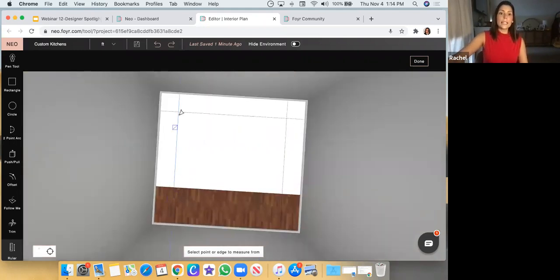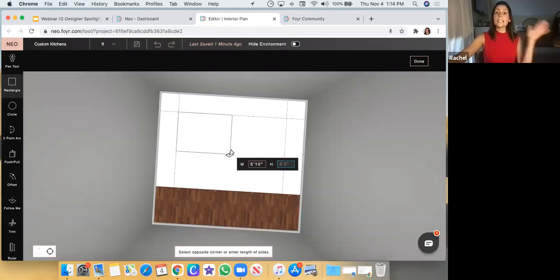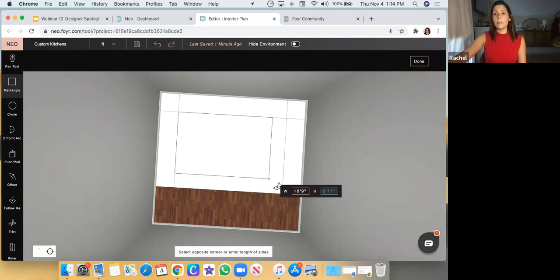Right? So now I have a nice dotted line guide that now I can draw over top and start to define the different areas. So I can use the pen tool, which will draw straight lines, or I can use the rectangle tool since I have a nice rectangle here. So that's the faster option. I'm just going to click onto the ruler and it's going to snap me into place using line snapping.